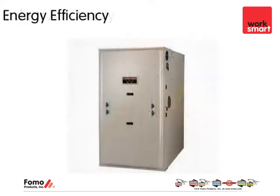As far as energy efficiency, I briefly touched on this. A very common trend right now within the heating, ventilation, and air conditioning industry is that, prior to coming into a home and determining the size of furnace or air conditioner that's needed, the first step should always be air sealing the home. The reason is that when you air seal the home, you're providing a much more efficient house that could potentially handle a smaller furnace.